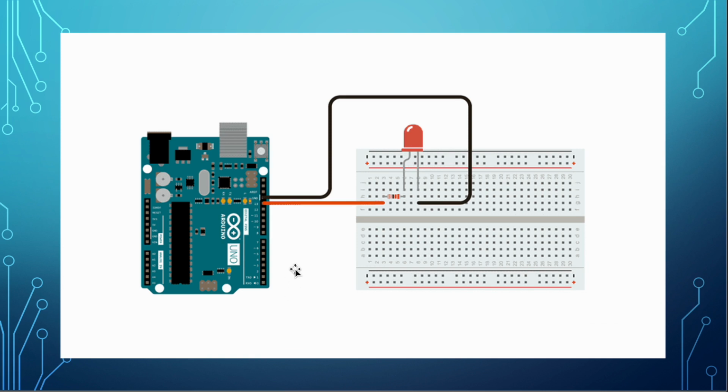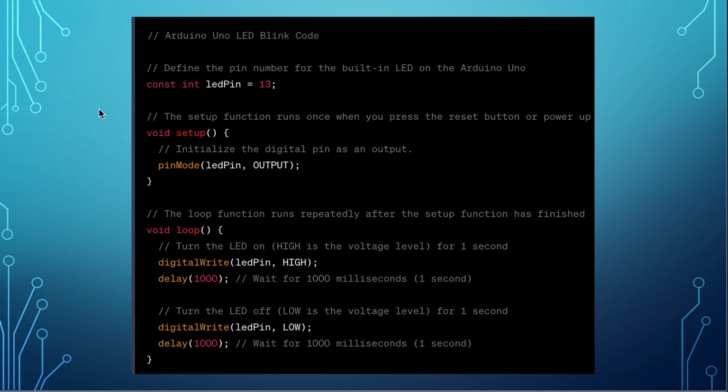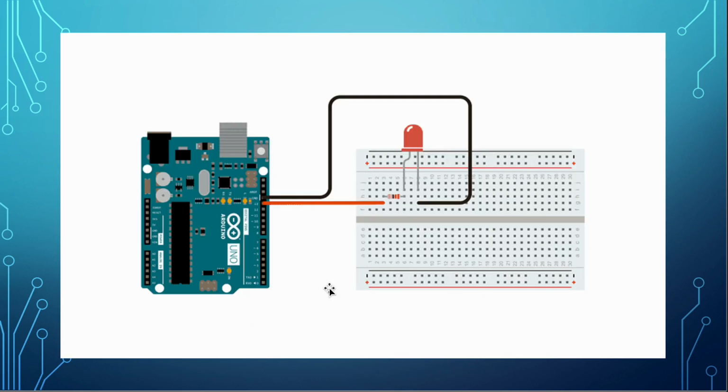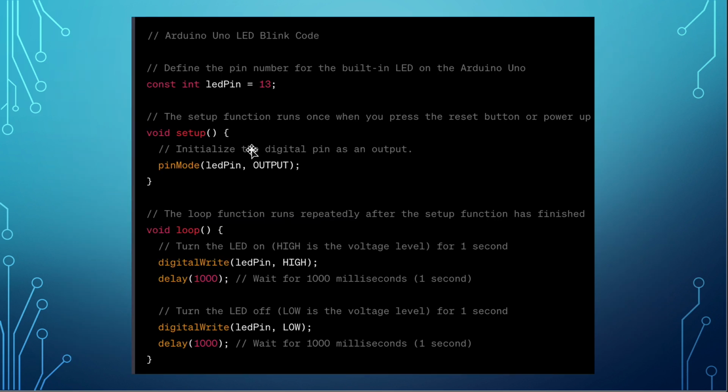It doesn't matter. The ground is always the ground. You can connect it here, there's another ground over here, you can connect it here, the function will be the same. You can connect it to 13, you can connect it to input output 10, 5, it doesn't matter. So if we connect it to 5, where should the code change? We have the code here. This code is written according to this diagram. We talked about it. Pin 13,